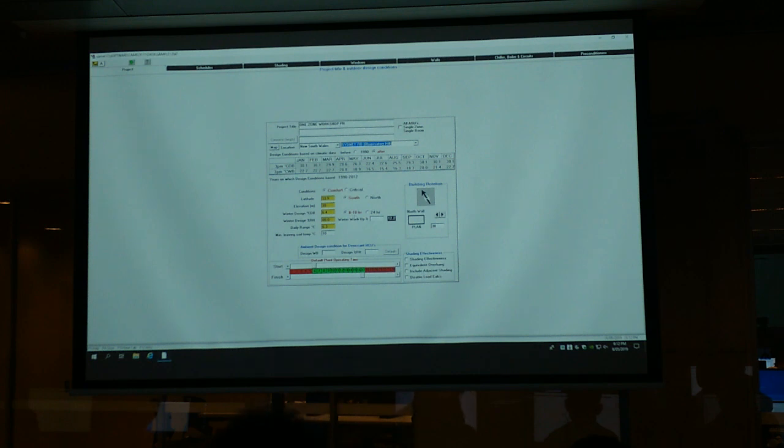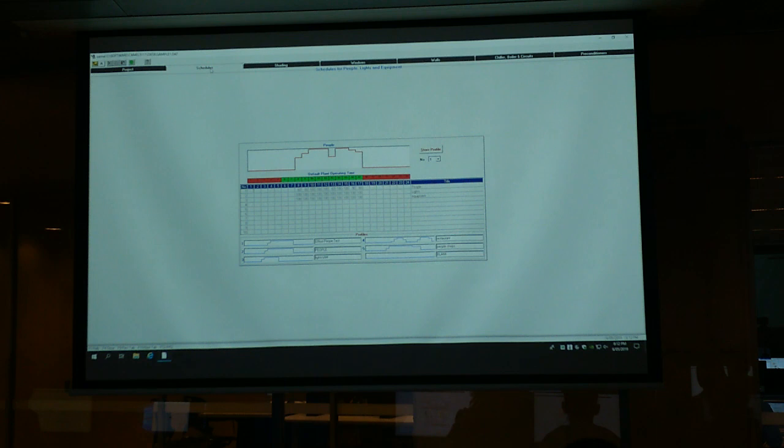And also select how many hours. I think in your project probably it's not 24 hours. You should choose the 8 to 18 hours. And then because we are going to mainly perform the cooling load estimation, so winter warm-up percentage as a method. Okay, so that's the first page. Okay, it's first page, and the second part, schedule.